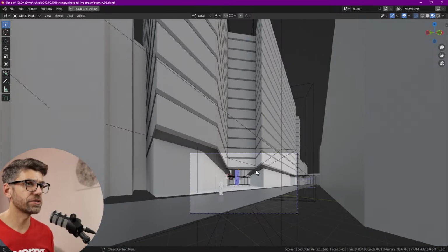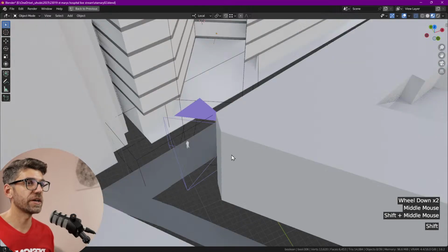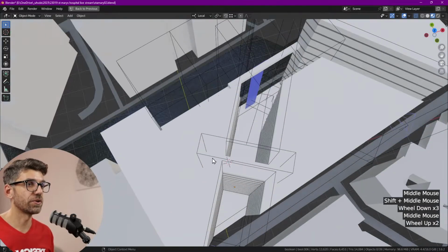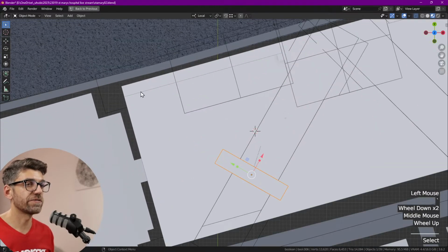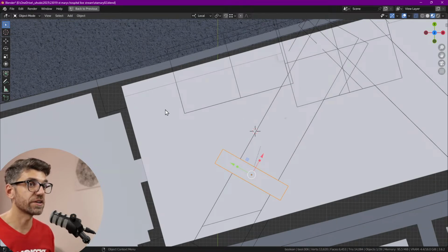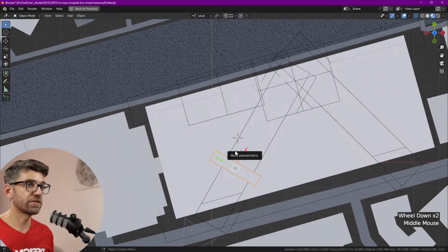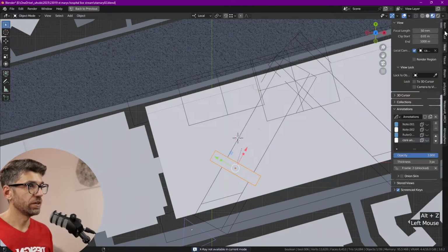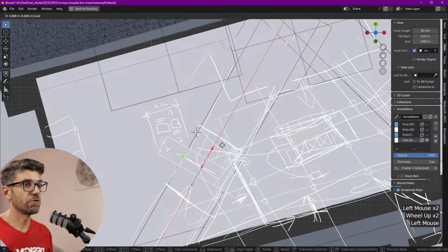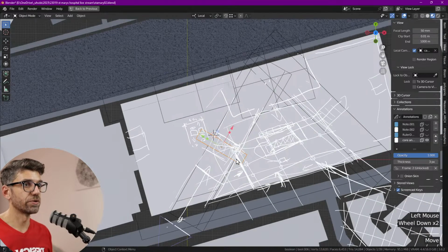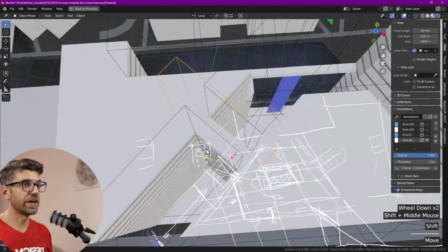And there are some regulations. I mean, we do have a fair bit of volume happening in this site, fair bit of area per each floor, so we might need a bit more. But that also depends on fire egress and fire regulations, because we are definitely going to need to have a core in here with emergency stairs, probably 2 of them, that can shrink down the width of this kind of corridor. Now, let's go and open our sketch here that we had and see where it aligns, because, yeah, that's what I thought. We might need to move this a little bit over on this side, so it's better aligned with where the core ends up.